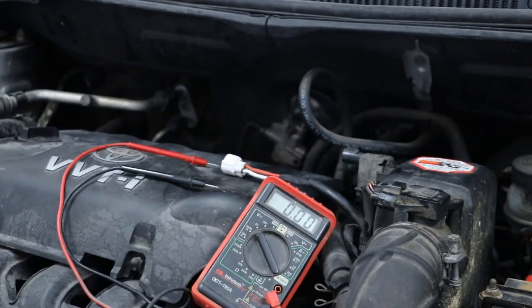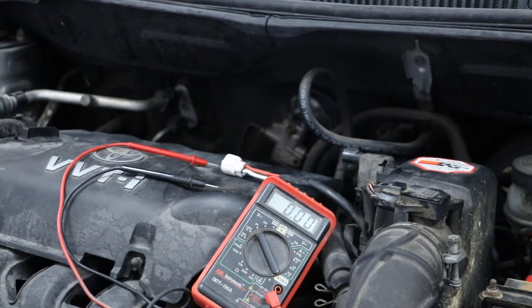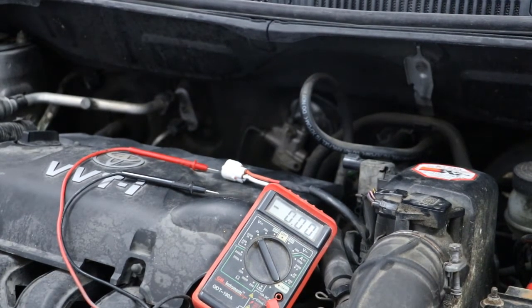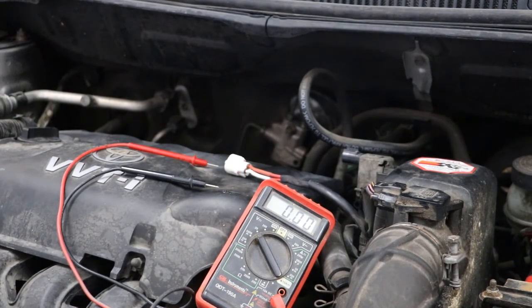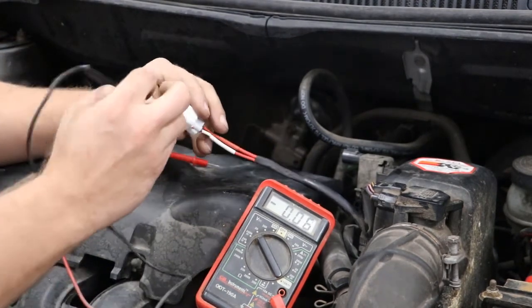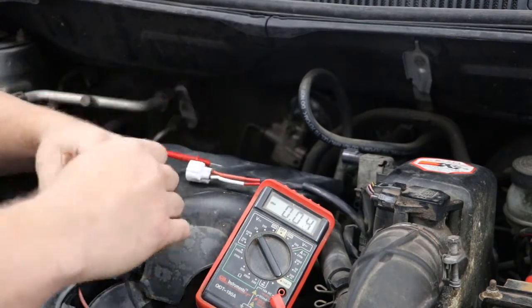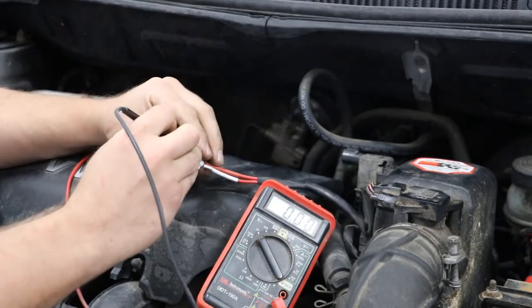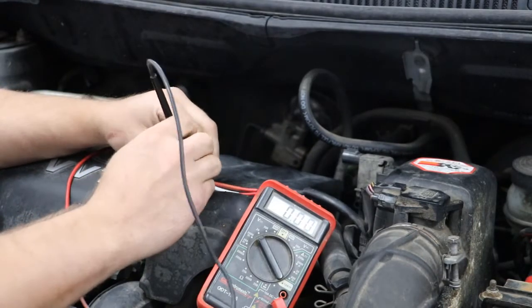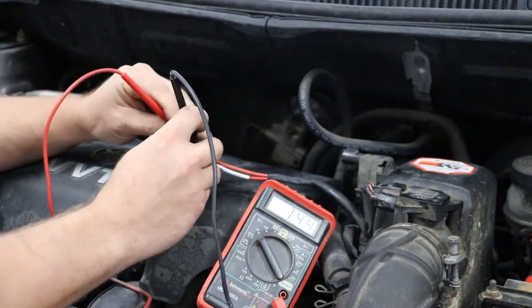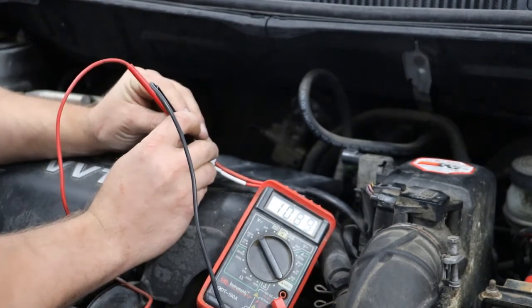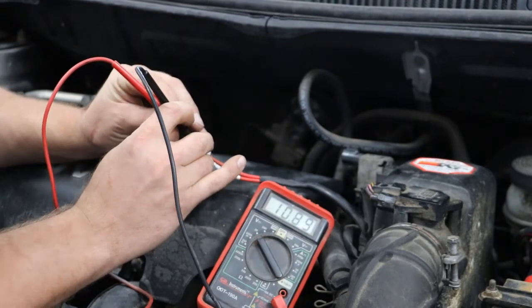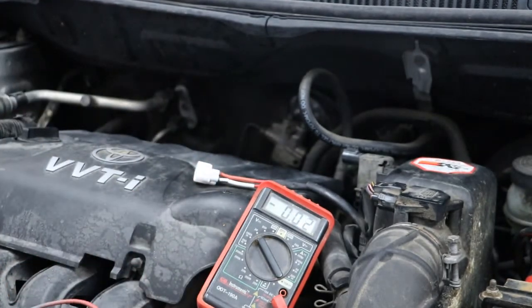Now we're going to turn the key on and perform the same test. The key is all the way in the on position and now should be receiving power to the solenoid. So now we're going to do our voltage test. One on the other. And as you can see, we're getting 10.89 volts, so we are getting some, and hopefully you guys can see that. We're getting almost 11 volts to the solenoid now, so that's great. So this should activate the solenoid, and means that we have a good circuit now.